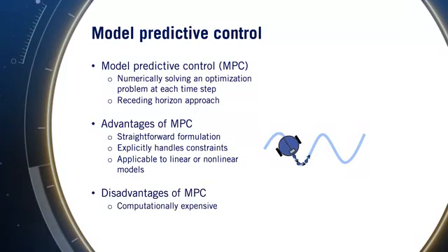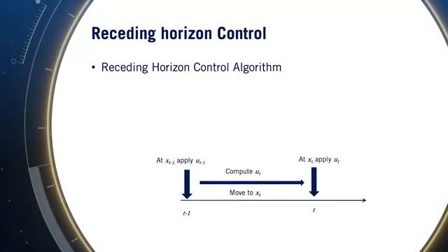The trade-off these advantages must be weighed against is that MPC requires significantly more computational resources than a static control law. It is certainly possible to create optimization formulations that are too expensive to compute at the high update rates required for smooth vehicle control. Careful implementation is needed to avoid overloading processors. Before we start designing MPC controllers, let's take a closer look at the concept of receding horizon.